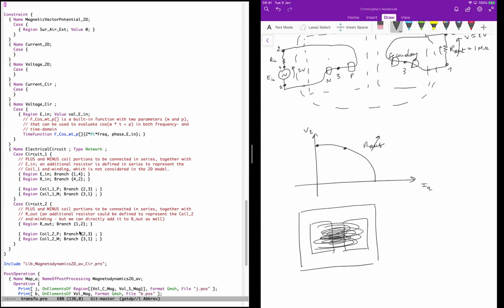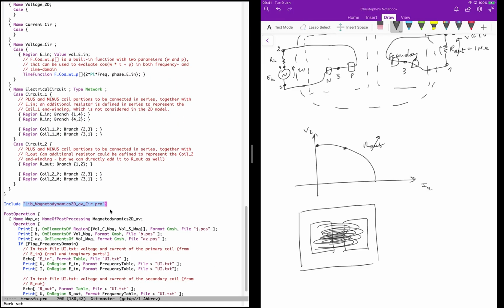And so what you will do in your homework is to model a 3-phase transformer. So we'll talk about it later, and we'll probably have some discussions about how to model a 3-phase transformer, but I will leave you to explore with whatever source you want how a 3-phase transformer works. So you'll have basically 3 pairs of windings, so primaries and secondaries for 3 phases, and I will ask you to do a design of these 3-phase transformers based on this template, right? Because you saw we haven't changed the template at all.